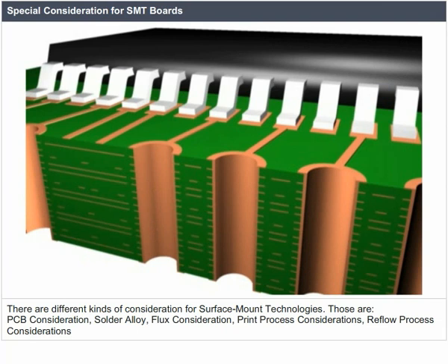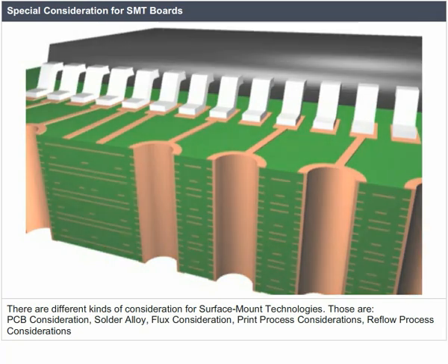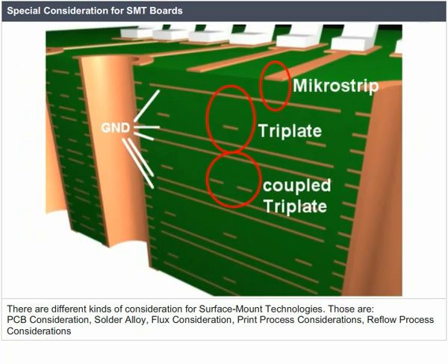Special consideration for SMT boards. There are different kinds of consideration for surface mount technologies. Those are PCB consideration, solder alloy, flux consideration, print process considerations, and reflow process considerations.